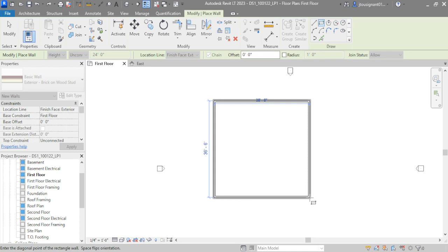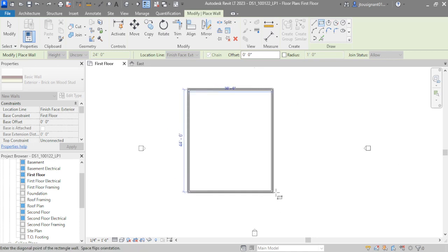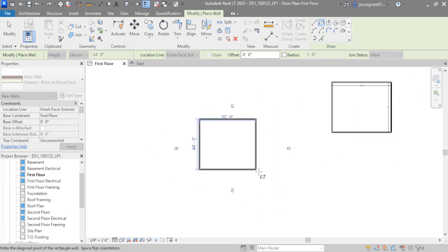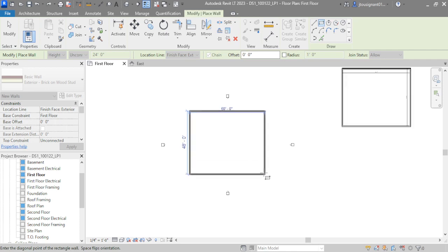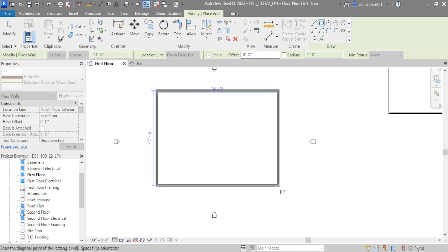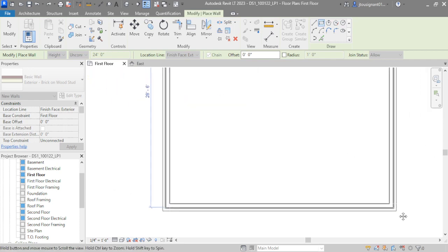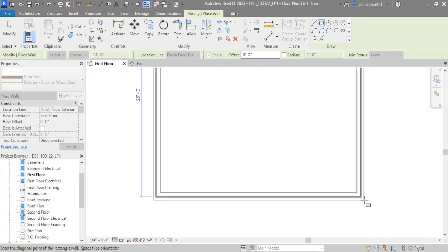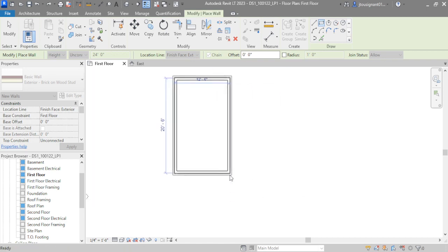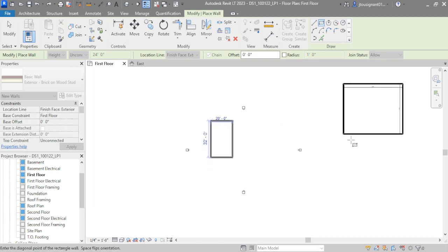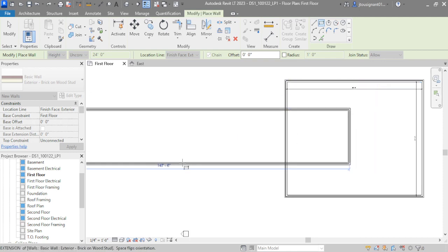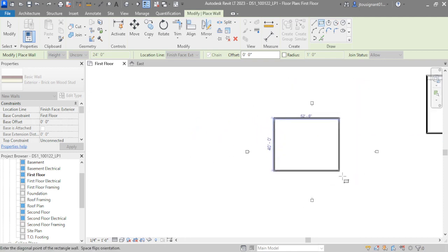Because for Revit, when you're zoomed to a certain distance, it's going to snap to basically feet marks. And it's actually jumping 4-foot increments when I move this. As I zoom in, it lets me move in 6-inch increments. But if I move in enough to where it's going to show me inch increments, I'm not going to be able to see my dimensions. So I'm actually going to say that unless you're doing a smaller building, it wouldn't be very easy to use the rectangle for this. But the rectangle tool does work for the way that I draw this.